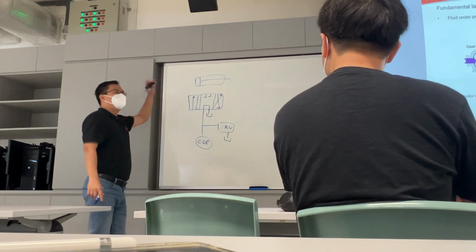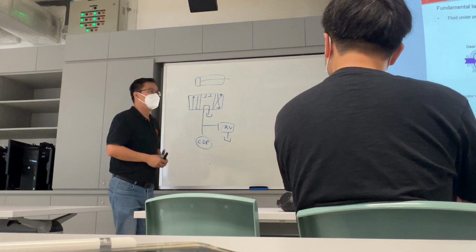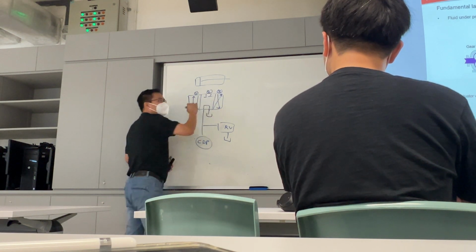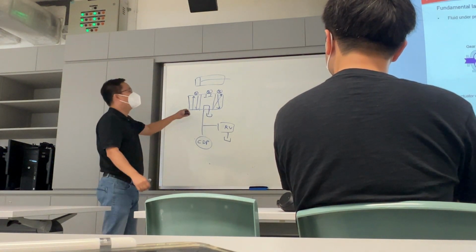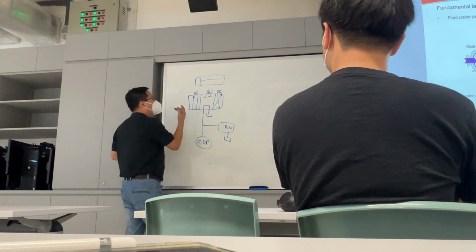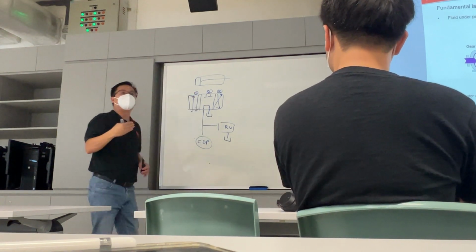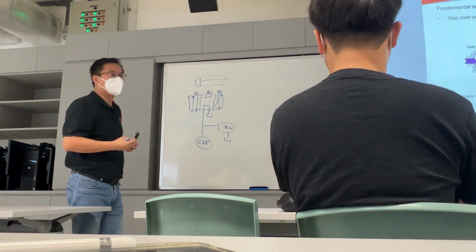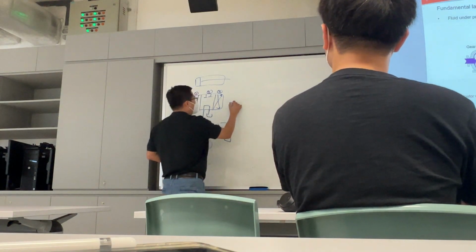Now, first of all, first question, how do you know this is a 4-way 3-position valve? Because you can position 1, 2, and 3. Remember the lever, there are 3 positions. If you can't remember the 3 positions, tell me how many squares are there? 3. Sorry, some of them look like rectangles, but 3 squares. Now, how many ways? There's 1, 2, 3, 4. So it's a 4-way, 3-position selector valve. This is the only one that I share with you so far. There's no 2-way, 1-way, no. I think 4-way, 3-position. Now, this selector valve.